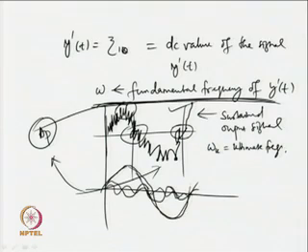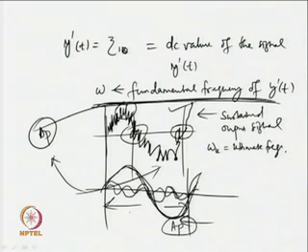But the analysis gives us a signal with the fundamental frequency. Now, I can make measurements on this signal, and that is a clean signal which can give us accurate values for the peak amplitude, and also for the instants of zero crossings correctly, from where we can measure the frequency or period of the signal. So, this is the concept, basically the way a curve fitting technique is used to extract a signal with the fundamental frequency from a practical signal.